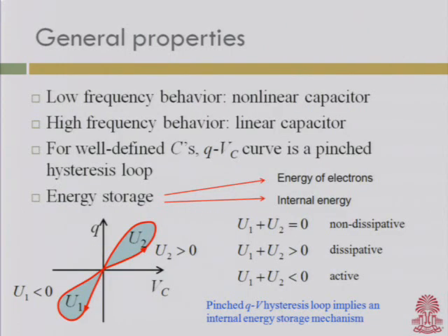Concerning general properties of these systems, we can mention their typical low frequency behavior. At low frequencies, a memory capacitor should behave like a non-linear capacitor. At high frequency, it should behave just like a linear capacitor. For well-defined capacitance, meaning non-infinite and non-zero capacitance, the QV curve should be a pinched hysteresis loop, which simply follows from Q equal to C times V.